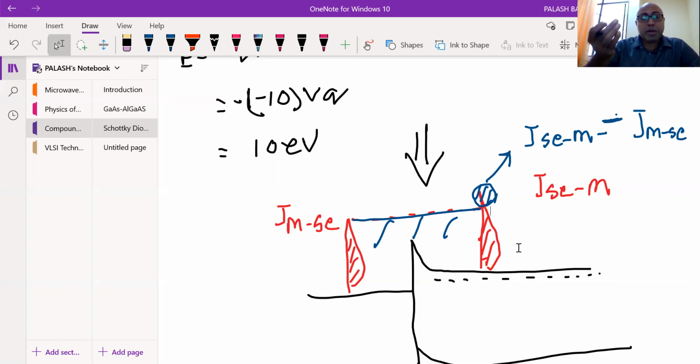Definitely, why we have not followed this for the PN junction diode is because if we try to follow these things in the PN junction diode, it looks very complicated. It's not so easy, because another term also comes in, so that is why we have not followed this method in the PN junction diode. But it doesn't mean we cannot do it. Once we know the process, then we can do it. So that's what I'm asking you to do now. But it is easy to do for the metal semiconductor junction diode because it has only one type of carrier, that is, the majority carrier.